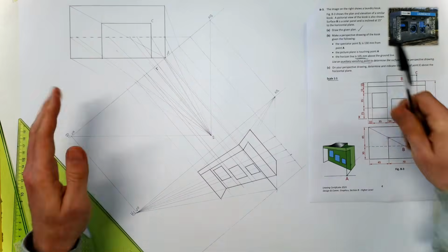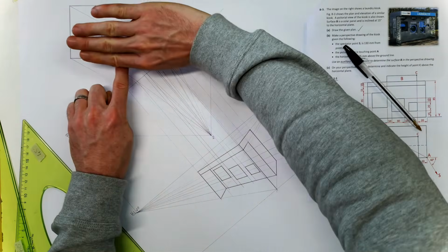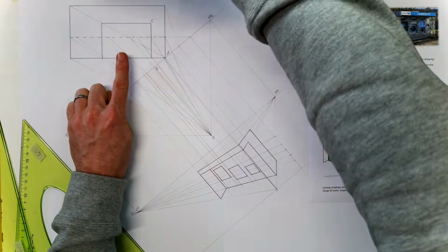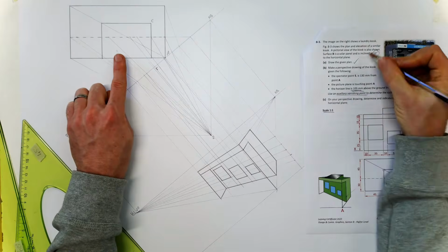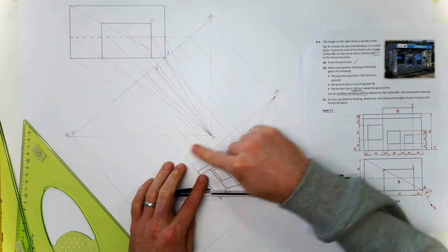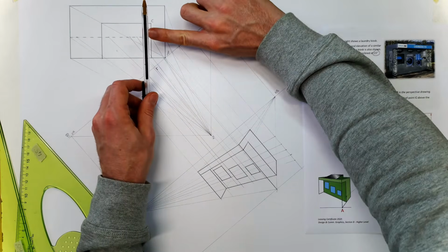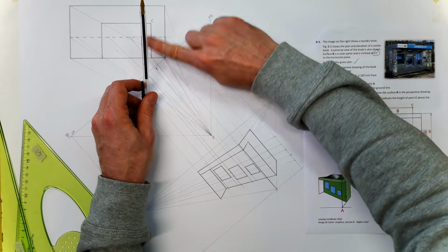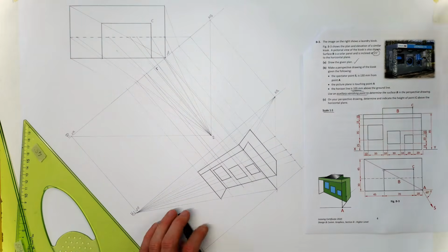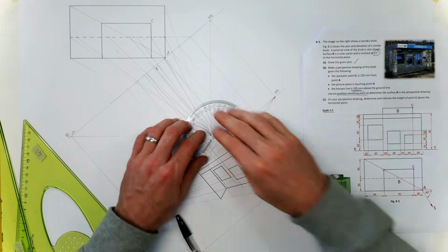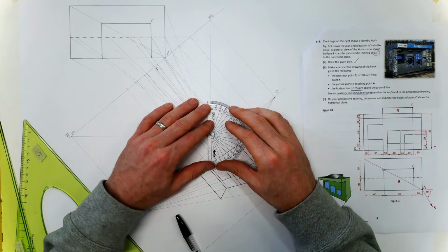If I was standing at this object and looking in this direction, I would just see a surface sloping away from me, so I wouldn't see that angle of 15 degrees. If I walked in around here and looked in, I would see that angle sloping, the 15 degrees created there. So this is the side that I'm going to do my construction on. Let's measure from my spectator an angle of 15 degrees.